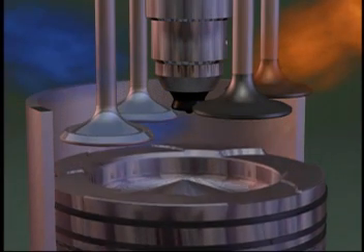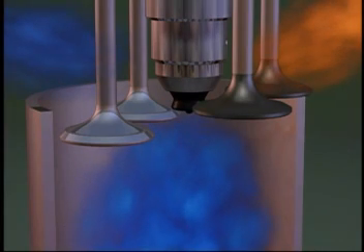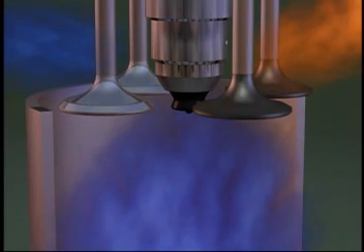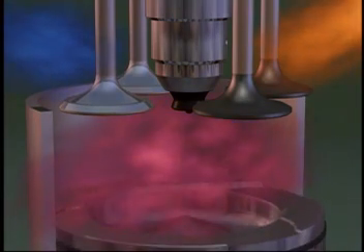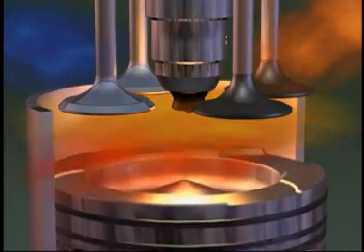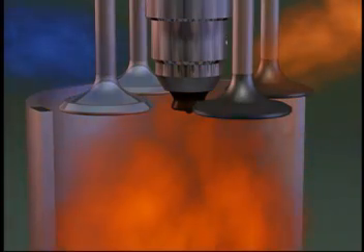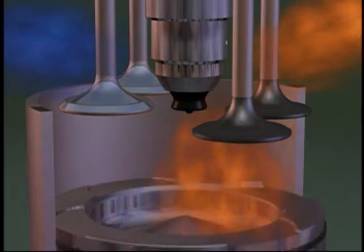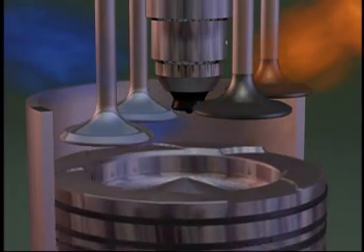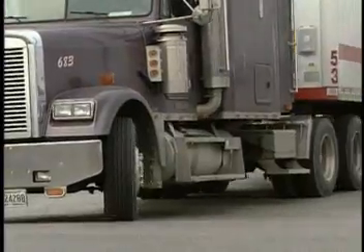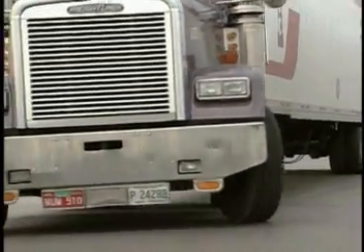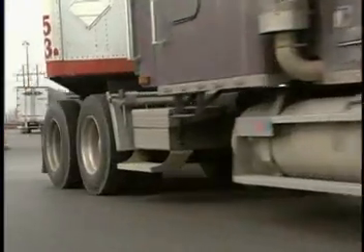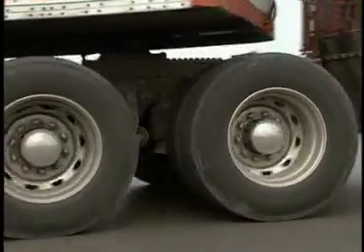As we stated earlier, there is a need to increase the cylinder pressure with EGR to maintain the power levels that were available in equivalent non-EGR engines. This increases the possibility of abrasive wear in the cylinder, as well as additional stress levels on other base engine components. With the possibility of increased wear and stress on engine components, lubrication oil will need to meet new standards.